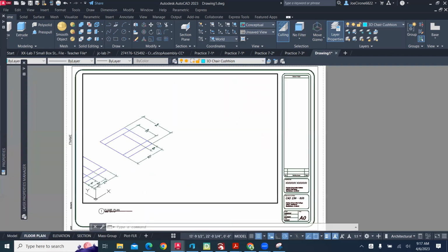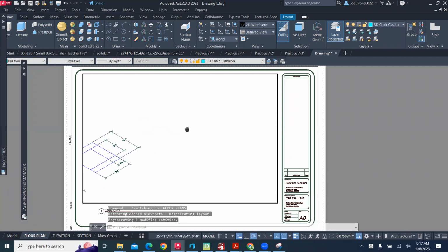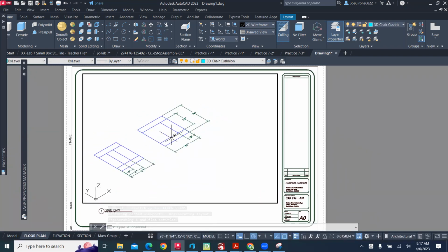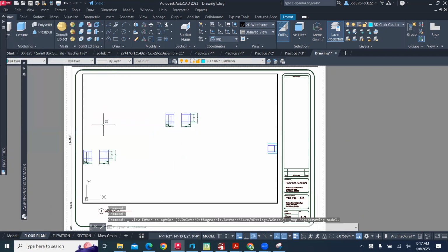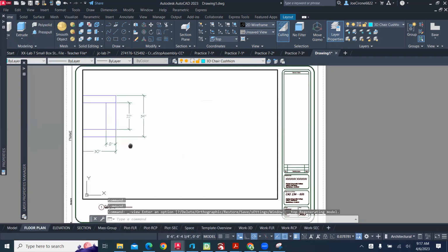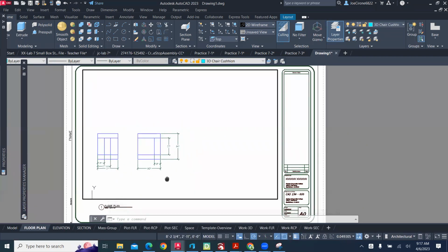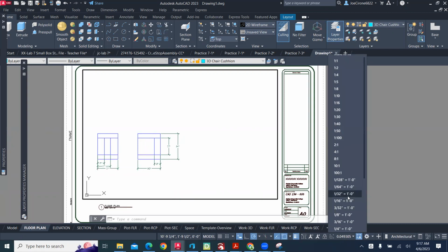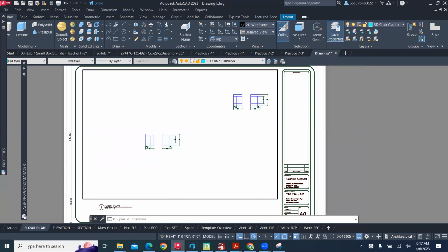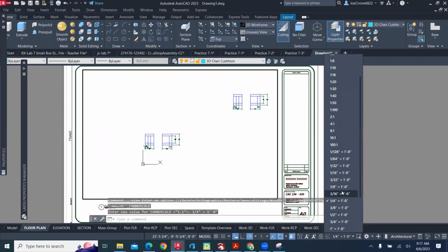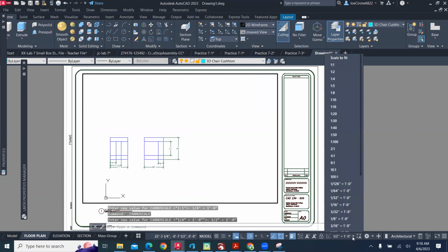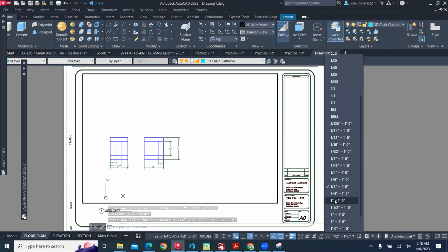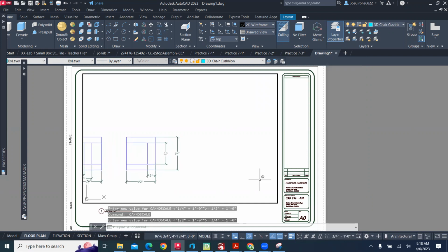we go back to the floor plan, we can then have a viewport with the information in top view. And so we can go and change that 3D view to a top view. And then we can bring that information, set a scale, and let's try 1/4 of an inch equals a foot, too small. And then we just bring it up from there. And so we'll go to 1/2 inch. And I like to use more of the paper. And so I just continue to bring that up to a scale that looks reasonable on the paper.